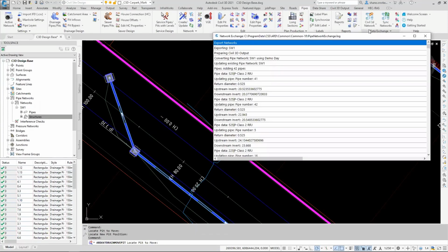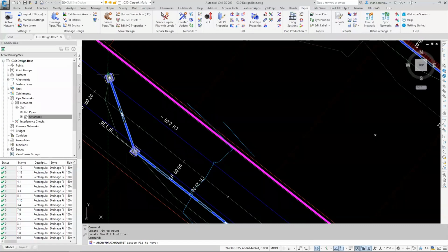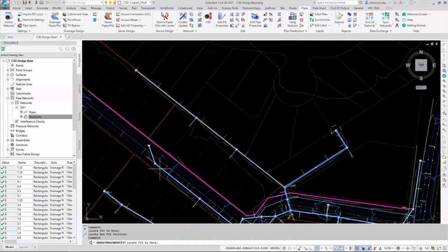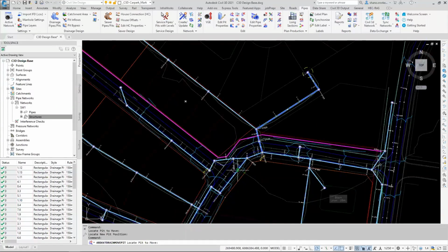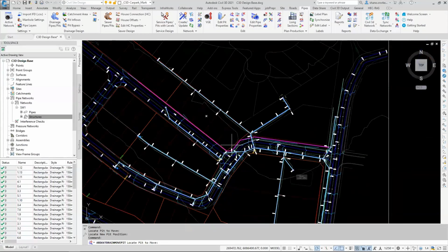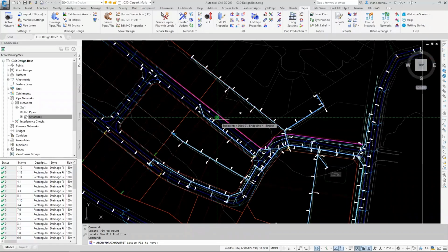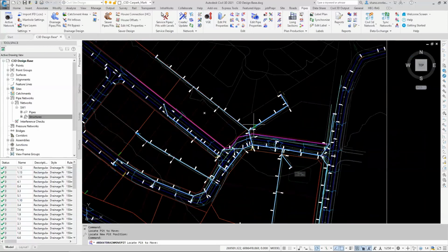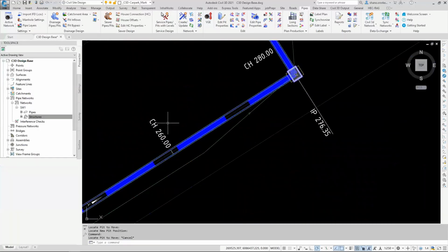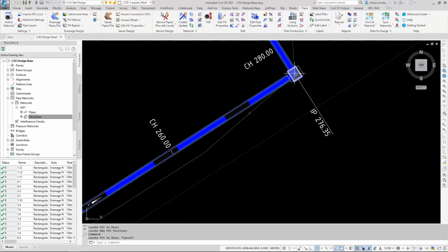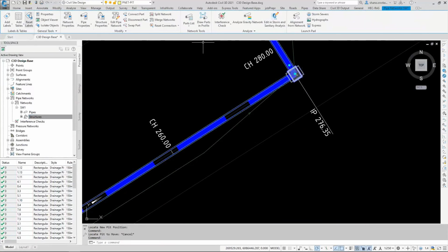So what you'll see is that network moves along and those changes are automatically accommodated for. It covers deletion. If you want to create, update, or expand the network, you'll also get that appended into the network at the same time. So in terms of edits, a lot of what is available in Civil Site Design is reflected now to the Civil 3D network.